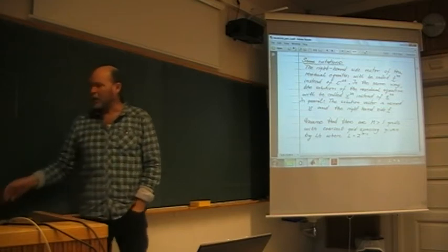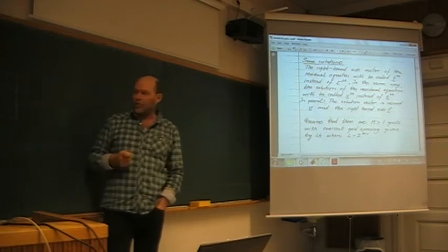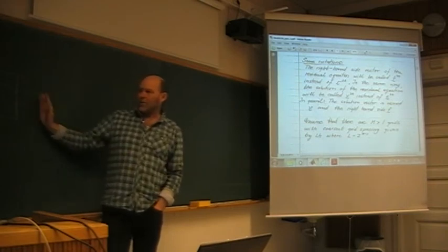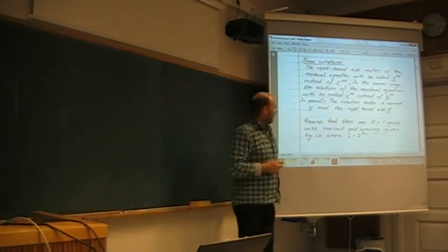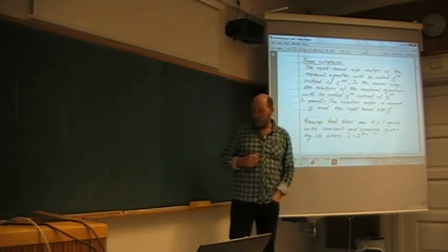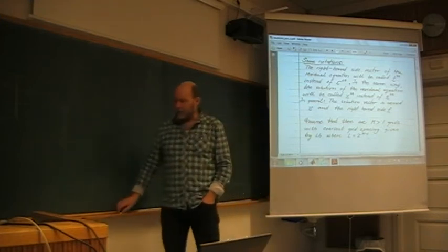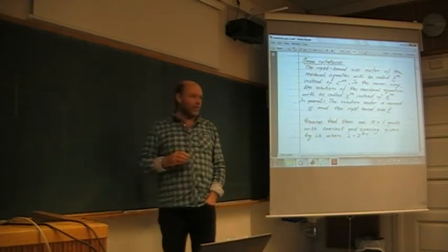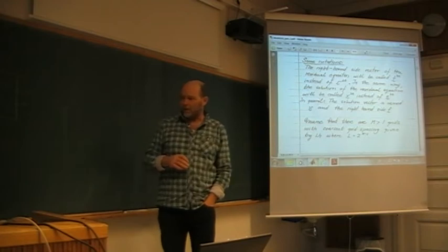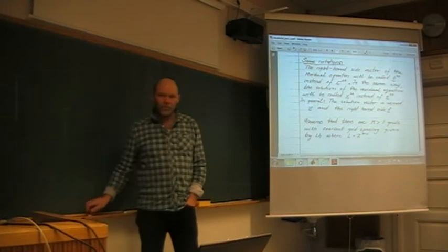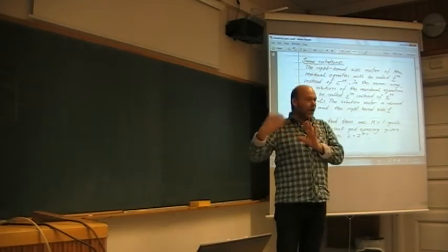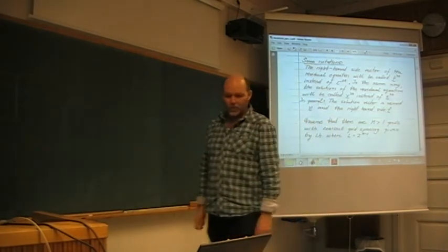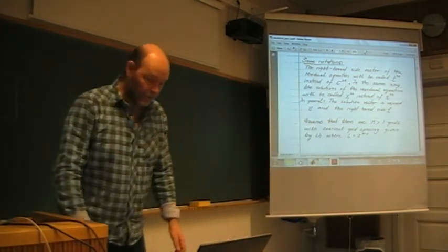So that would be one way to easily construct your geometry, starting with the coarsest possible mesh and then just divide and divide and divide. Normally people use a factor of 2. Nobody has said that is gospel. You can actually use any dividing number. I know the square root of 2 has been tried. Of course, to double the cell size or halve the cell size is much easier. So a factor of 2 is very, very common.